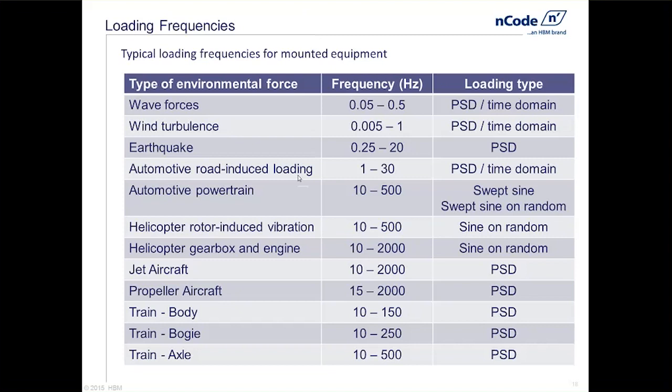The loading type can be described in the time domain. It can also be described in the frequency domain with the PSD. If we get into some higher frequency ones, maybe some aircraft applications, jet aircraft, we're looking at frequencies that are 10 to 2000 hertz. Many times we're describing that loading in the frequency domain as a PSD. Perhaps some of the reasons there are it's going to be computationally more efficient.